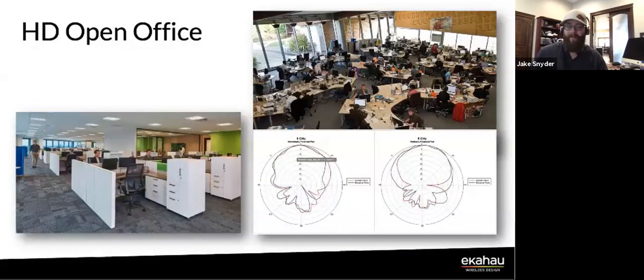The other thing is that using directional antennas, I'm going to increase the SNR of all my clients by 3+ dB because I'm going to hear them better. They're going to hear me better. And as you get through this, there's no scenario where an omnidirectional in a big open office is going to be a better performing network than a directional. There's not really a place where that happens.